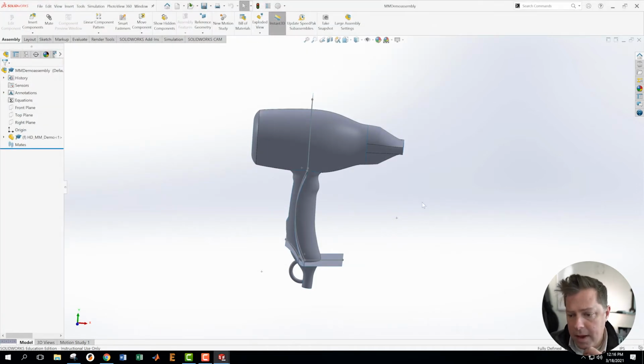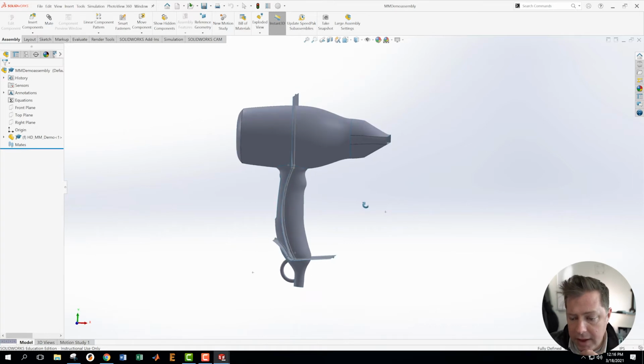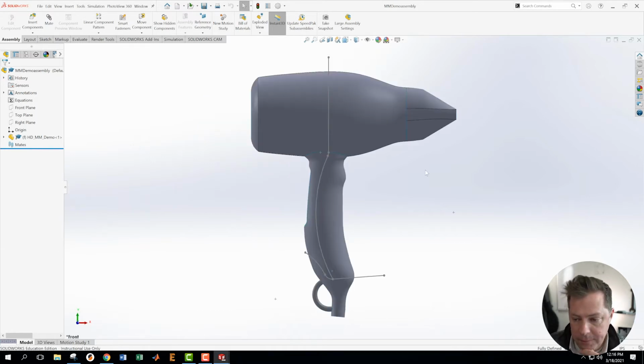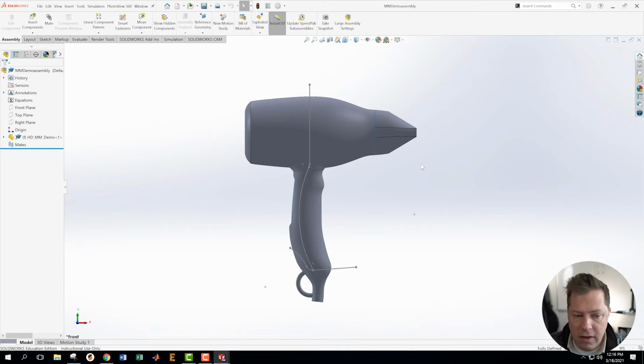It's important when you're doing master modeling to make sure all your file naming is good, because with master modeling, what you're basically doing is linking a bunch of files together. So this is not a spot where you want to be careless in terms of how you're naming things. Okay, so I now have this single part in my assembly.